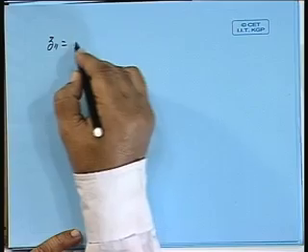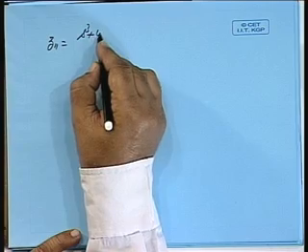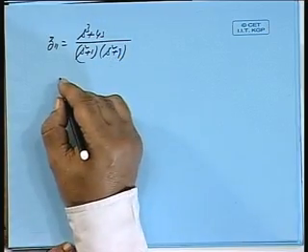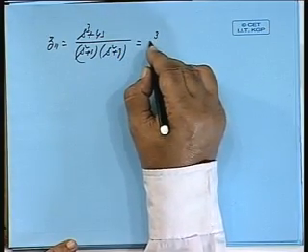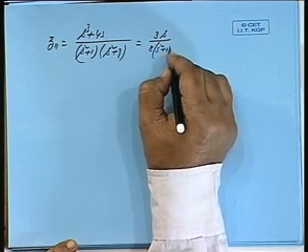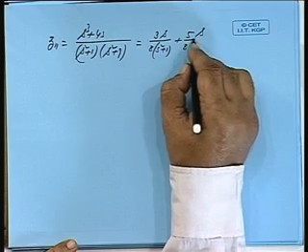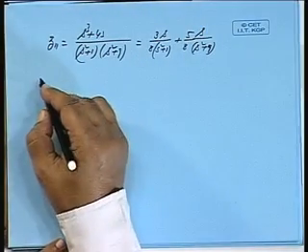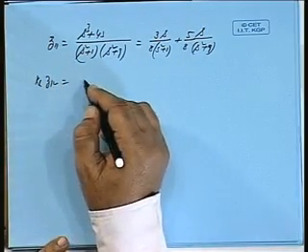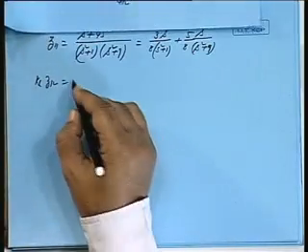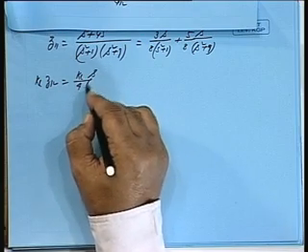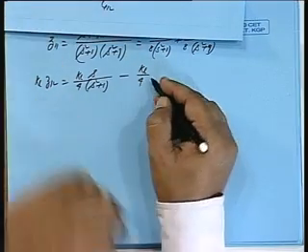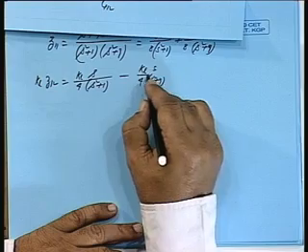Z11 is s cubed plus 4s divided by s squared plus 1 into s squared plus 9, which has given me factors like 3 by 8 s by s squared plus 1 plus 5 by 8 s by s square plus 9. We will very soon see the effect of KL, and KL times Z12 will be KL times 1 by 4, KL by 4 s into s square plus 1, minus KL by 4 s into s square plus 9.